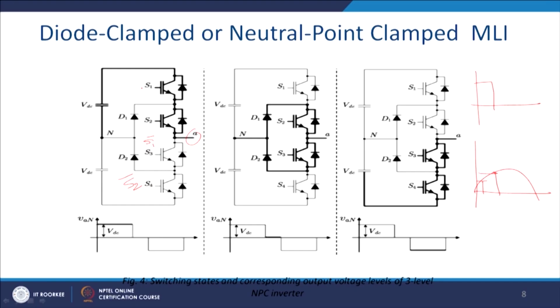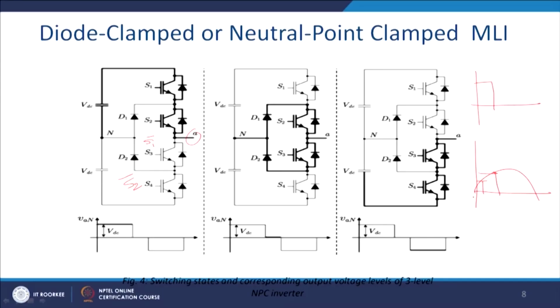For this reason, if you do not have an extremely poor power factor, generally it is in StatCom that this is a challenge. Otherwise, voltage and current both will be positive. Only in StatCom they are 90-degree phase shifted, so there is a challenge, because when one voltage is at its peak, the current is 90-degree phase shifted.